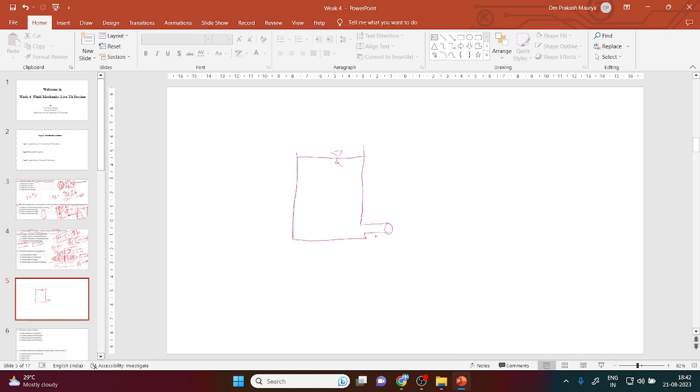We cannot apply it for that type of question. If someone tells you to apply the Bernoulli equation, the assumption is already given. The flow should be steady, and you can apply the Bernoulli equation. Just for the sake of understanding, let's say your water is flowing like that. But for an open tank, it will actually be unsteady, isn't it?